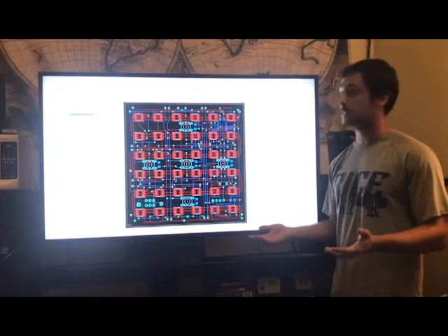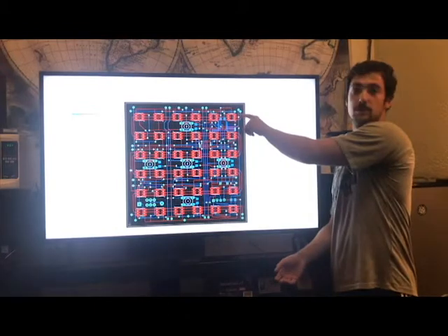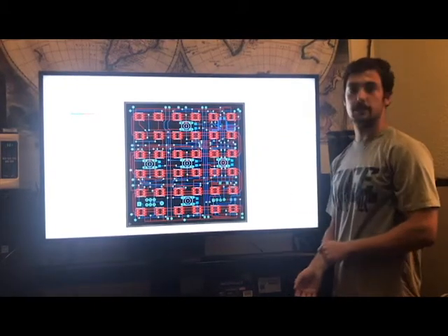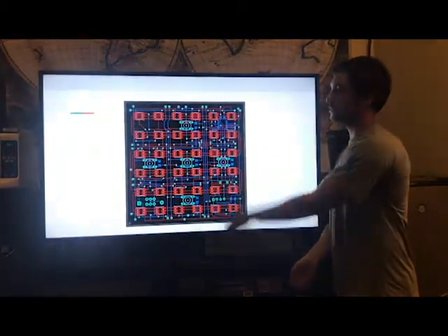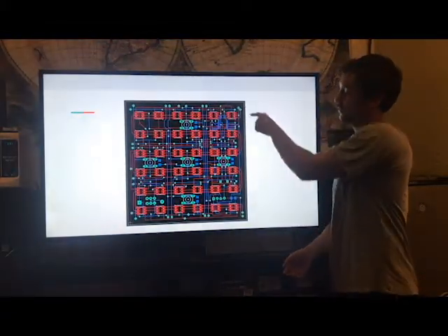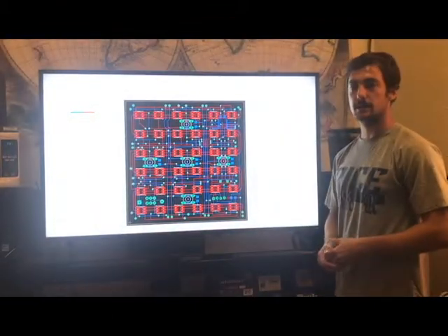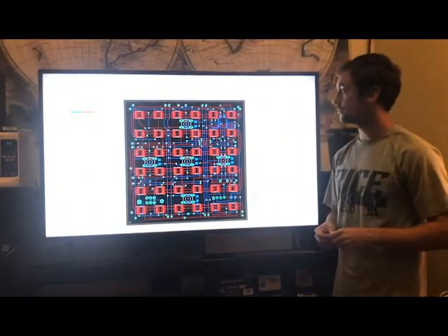And this was our final PCB design. The MSP430, seen in the top right, would communicate with the first LED on the grid. The buttons are connected to vertical and horizontal traces, and we were able to route out the signals that would be necessary to interface across the faces in a very comprehensible manner.